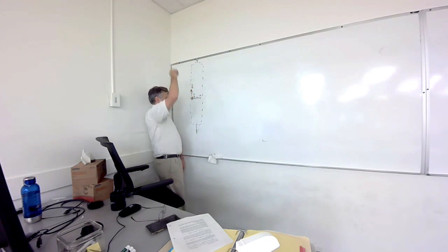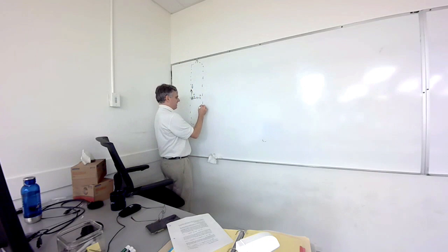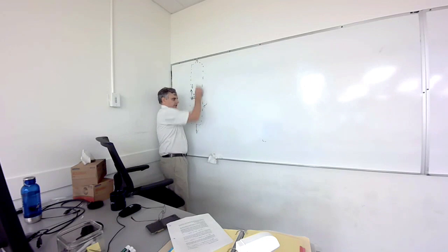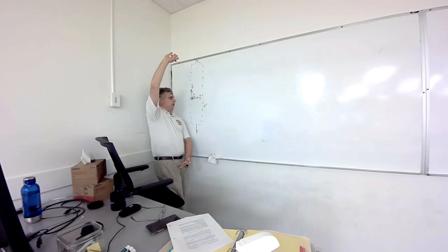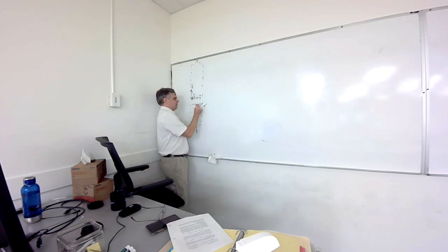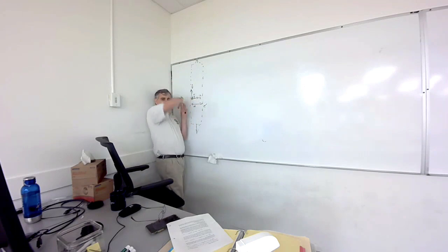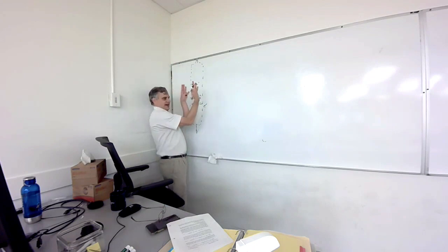So it's infinite in the z direction, and I'm going to specify the tangential fields E and H across this facet and this facet. So this would be infinite in both z and y. There would be some separation distance d, and then there would be another plate over here, which I'm going to let go to infinity in z and y, and that should identify a bounding surface.